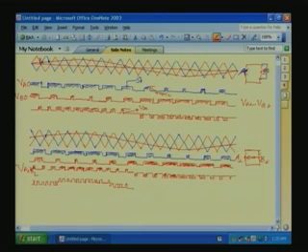So, why am I summing? This is not actually happening in the converter; these two waves are never summed. But when you sum them, the frequency spectrum of the resultant waveform approximately gives the harmonic spectrum of the suppressed current waveforms. We can get a feel for that if you do the FFT of this one. So, this is a stepped waveform, PWM with a stepped waveform. This waveform will not contain FC and its harmonics; FC, 3FC, 5FC and their harmonics will be highly suppressed, and then the sidebands at 2FC.